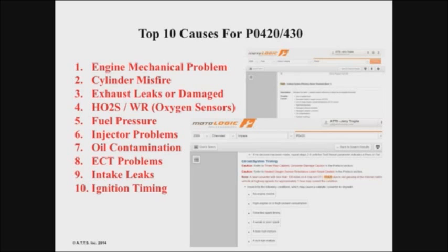This is such a huge problem out there that a few manufacturers, that we'll get to in a second, have put in their scan tool the ability to do relative compression, to check to see if that cylinder is good or bad. Now, some people have the IDS or the TechStream or some other tools that are out there, but what happens if you don't? I'm going to show you that.